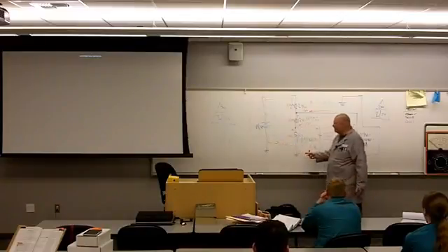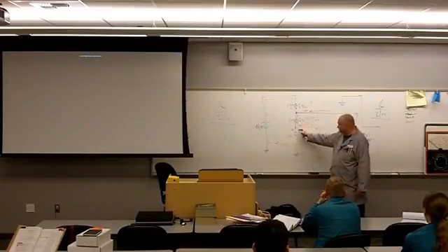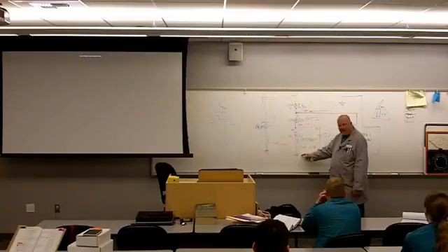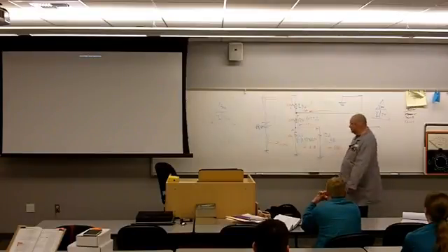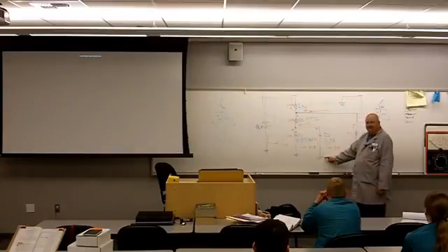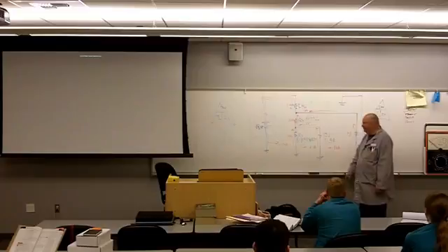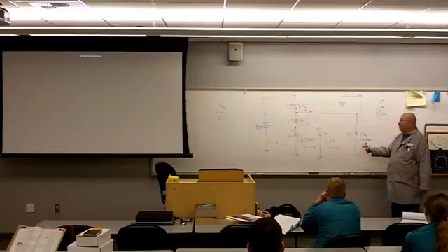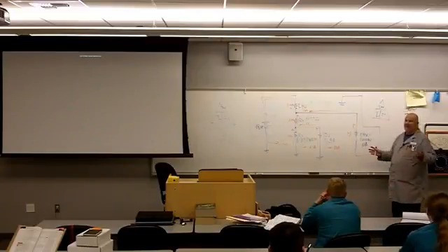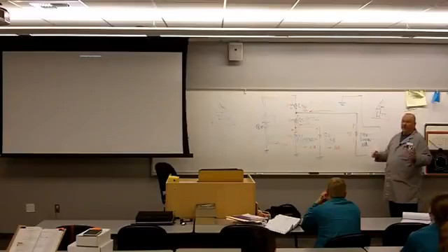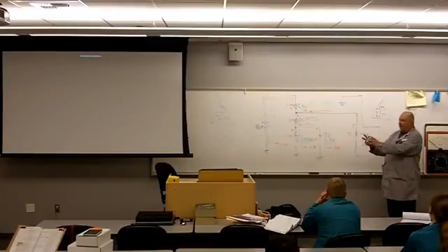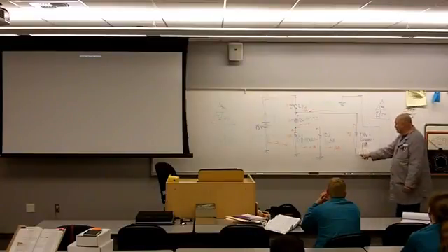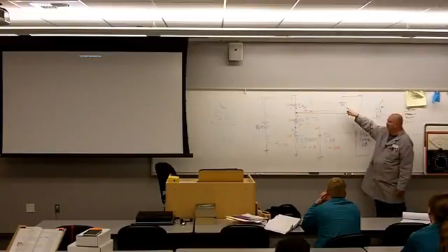Circuit's going to operate exactly the same. We're going to get the bottom of the circuit here, the bleeder resistor, connect that also to ground, chassis ground. Okay? We're going to connect the negative lead of our radio directly to chassis ground. We're going to connect the negative lead of our radar. The radar's kind of mounted in an unusual position, you know. I got the pulpit up there. I drive the boat, I want the little radar there. So I'm going to have to run quite a bit of cable, but I'm still going to connect it to chassis ground.